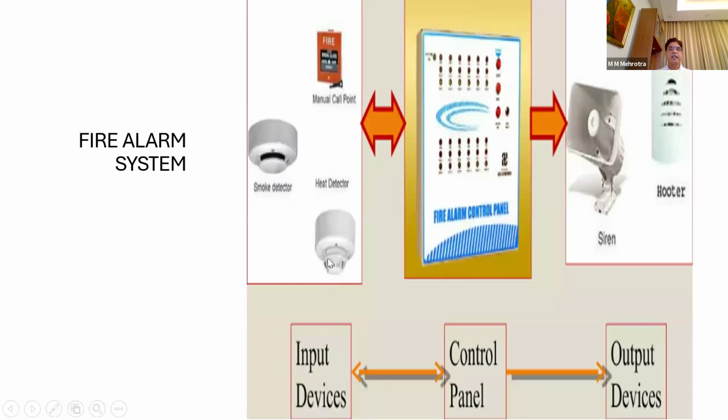Heat detector, it sees the temperature. If the temperature is some 57 degrees to 80 degrees, it will activate. In normal conditions, temperature may go up to 55 degrees or whatever, but environmental temperature will not rise to that degree. That ground is normally at higher temperature. Okay, so what will happen?